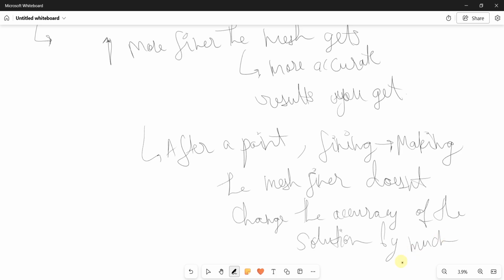So let's say that for the value of thrust, I'll just call it mesh. First it was a coarse mesh 1x, so it gave me around 2500 Newton. Then I made it 10x medium mesh, so I got 2220 Newton.